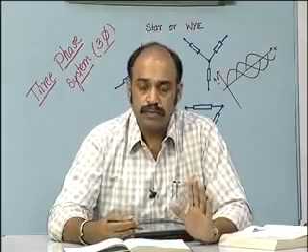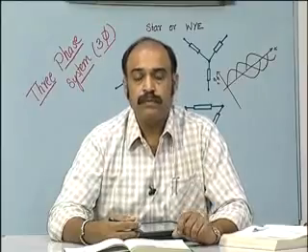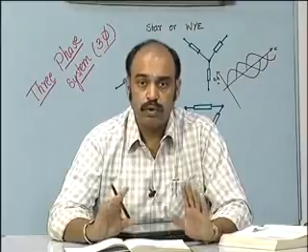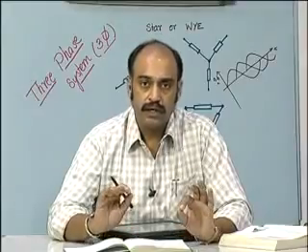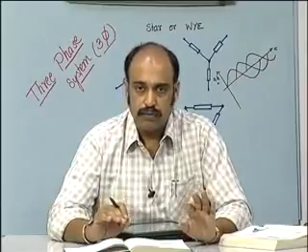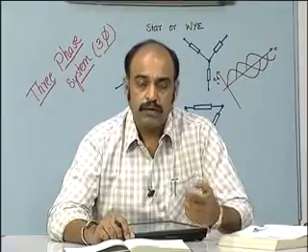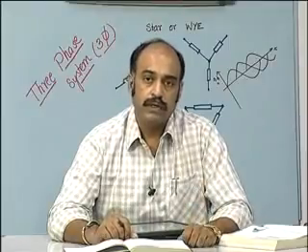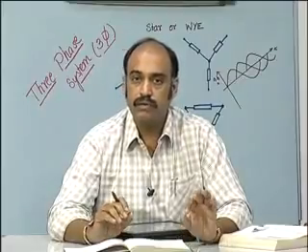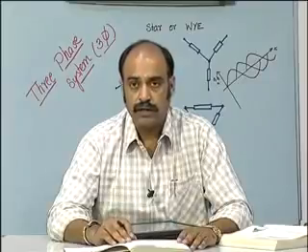And then we discussed the measurement of power. The best method to measure the power in a three-phase circuit is by means of an oscilloscope. You measure the voltage and current together using a voltage probe and a current probe, that is, the line voltage and the line current, and then compute root 3 EL IL cos phi, where the phase difference can be obtained from the voltage and current waveforms seen on the oscilloscope. That would give you the best method. It is independent of whatever the power factor is.